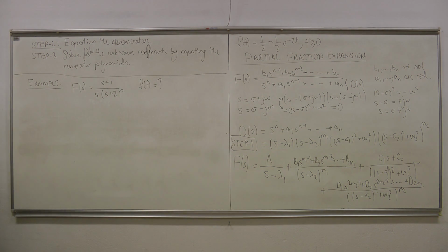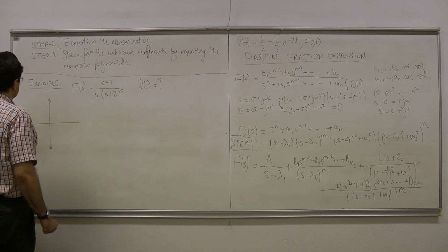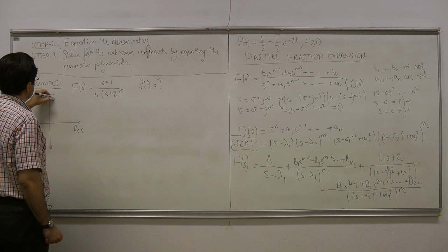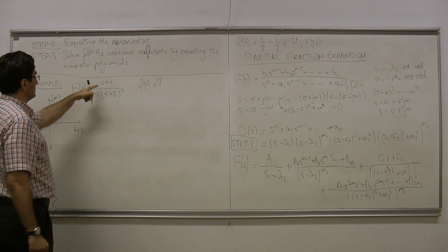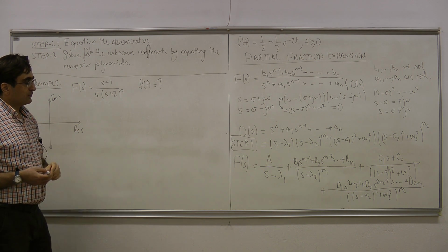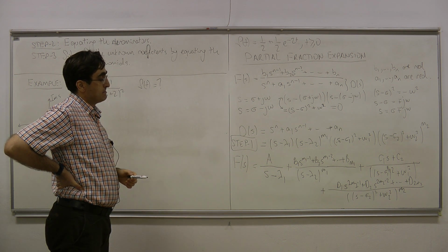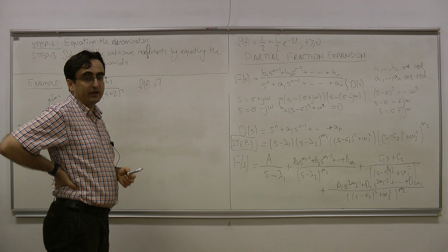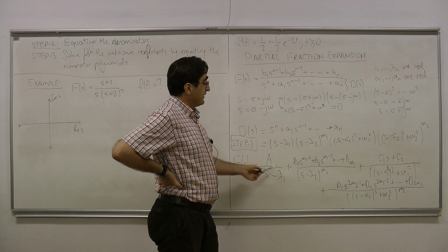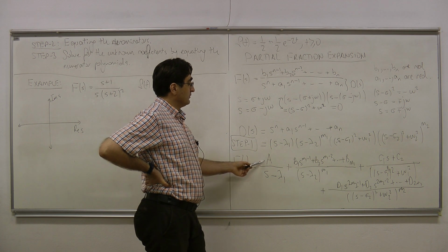So now let us apply inverse Laplace transformation. But before we try to take the inverse, I'm first going to make a pole-zero plot here. The zeros are not going to be that important, but what are the effects of zeros here? Do you think that zeros affect the inverse Laplace transformation in any way? Yes, actually, the answer is yes. Zeros do not affect the denominators of these terms here, but zeros are going to affect these coefficients.